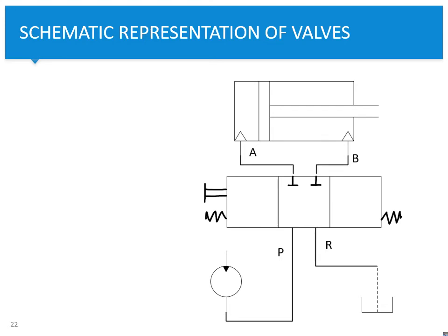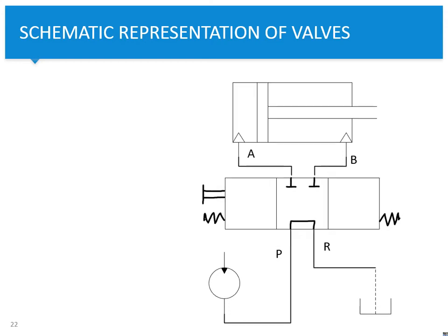There is a problem, however. If I have a pump in this wheel loader running, and I block the flow, then of course my hoses and whatever wouldn't live very long. So I'm going to do something I think is really clever. I'm going to connect the pressure valve in the rest position directly to the return valve. So like this. So when the cylinder is not activated, oil is directly pumped to the return valve.